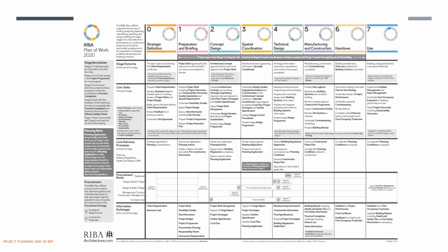You studied cost planning, that means the elemental and historical cost analysis. Those things we do in the first and second stage. When we prepare the brief, then we move to concept design. Concept design is not a detailed design, but this concept drawing has the detailed requirement of the final output, because from this stage we are going to start the detailed design and the main important process, the tendering process.